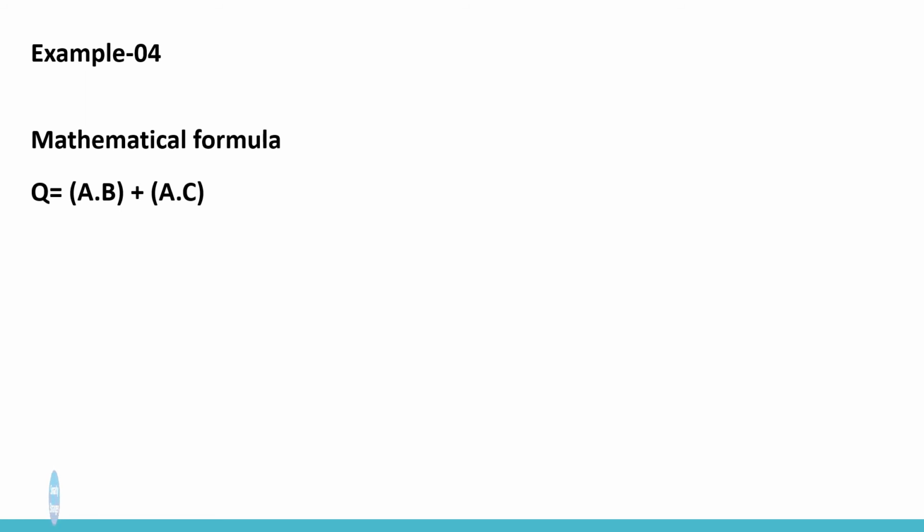For example, we want to convert a mathematical formula, Q equals A.B plus A.C, into ladder diagram. Here we have 3 inputs and 1 output. Now we make a program.